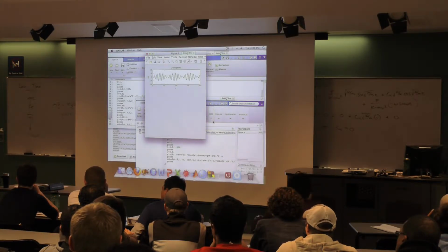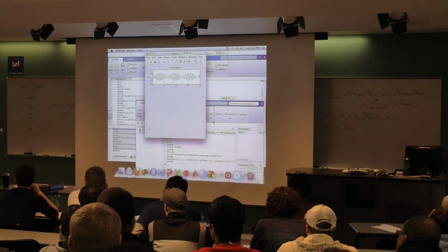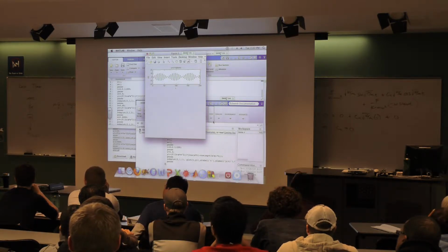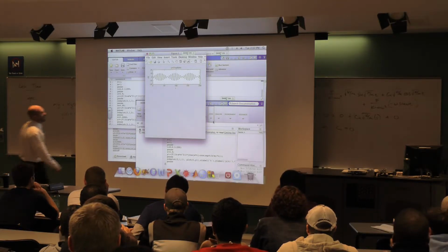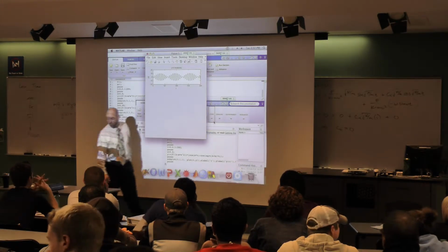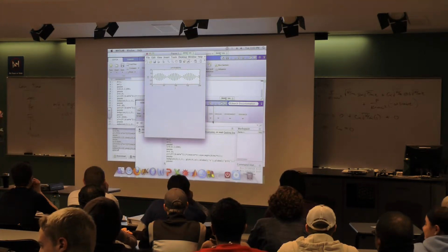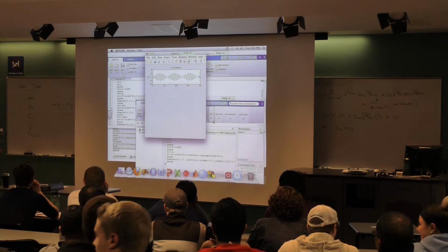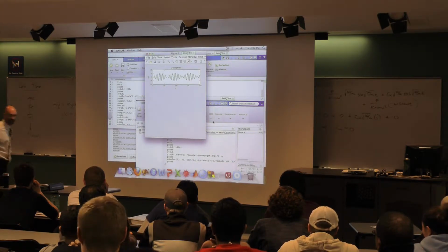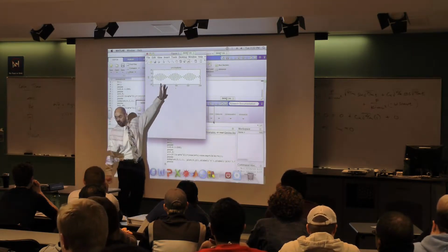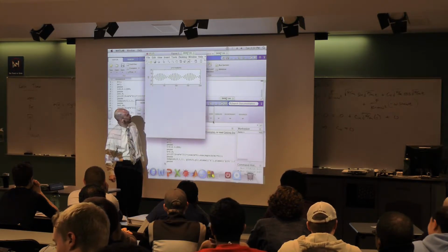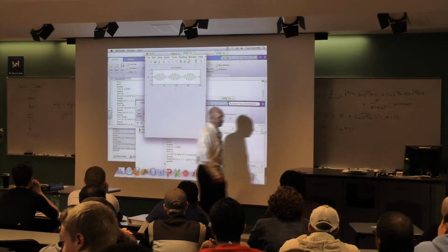If you sit right at the 57, what probably is going to happen is something like this. It'll shake a lot, then it'll shake a little bit less, right? And a lot. It's the amplitude we're talking about. And in fact, you can experience this acoustically too. If you're a musician, you can try applying excitation to a string instrument close to its frequency, and you can observe this in an audio way. So, kind of cool.